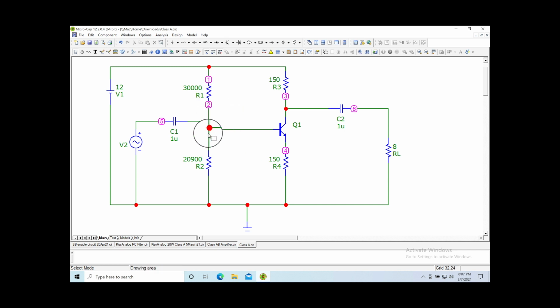Now, besides setting up a voltage level, they're also supplying current. Like I said, current comes down here, a parallel path. A little bit of current goes in this. Well, that means that we have to have enough current going this way to drive this transistor that's going to drive this stuff. When we look at 30K and roughly 30K, we have roughly 60K coming off 12 volts. So there's not a lot of current coming down here. So this guy better have a lot of gain, because there's not a lot of current feeding that. So that's something you might want to look at, lowering the value of those.